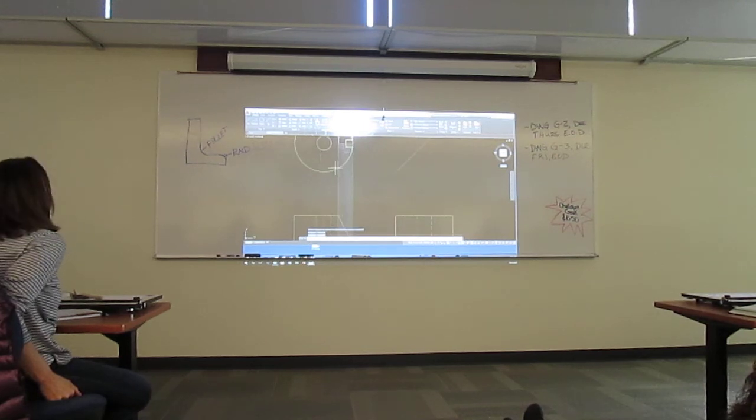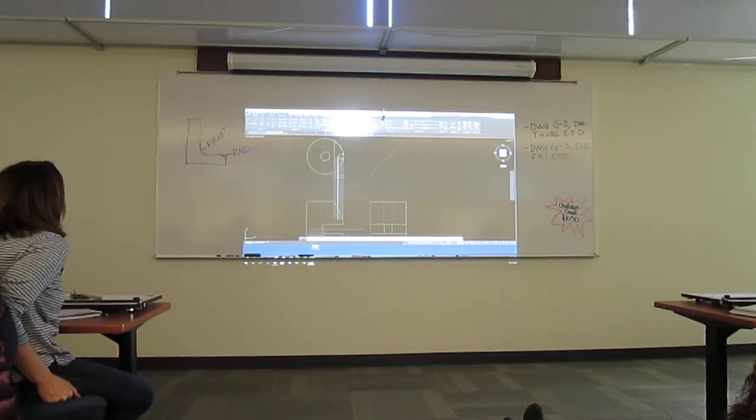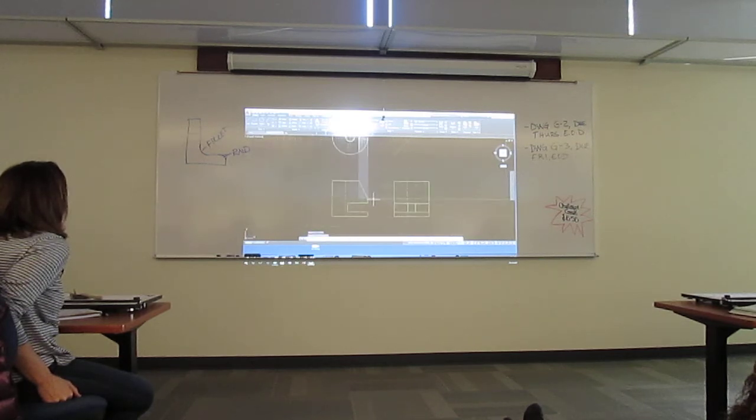So I've defined a bunch of points here, right? I projected down in here and I see the same points, correct? Okay. So now I have to locate those points over here. Now I'm only going to do half the curve because it's symmetrical with this half, correct? Okay, so how I'm going to do this is I'm just going to come over here. I'm going to grab this point, I'll shoot it over, and I'm going to change color on these guys so I can keep track of these because I'm going to get a lot of lines here in a hurry. Okay, so the cyan ones here will be my height grid.